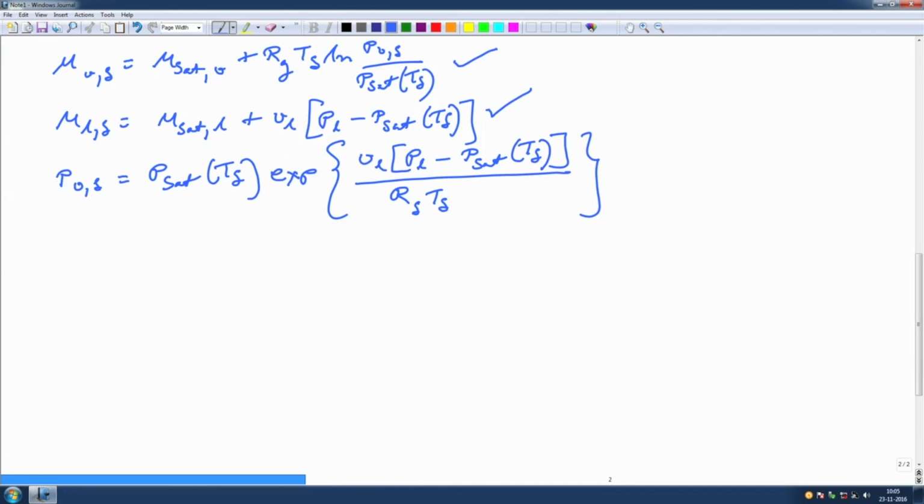So, the pressure difference now in the liquid and the vapor phase can also be given as the sum of the capillary pressure and the disjoining pressure. Capillary pressure comes from the curvature effects, that is, as we said, for a flat interface this should have been the same, whereas the disjoining pressure comes because of the thinness of the liquid film.